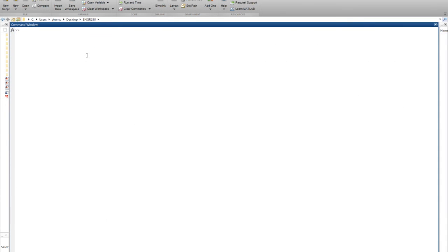Okay, the key for working with complex numbers in Matlab is that 1J is what Matlab calls the imaginary unit. Right? So every time we write down J, we're going to actually write down 1J. So I'm just going to enter the matrix that we had. I'm going to call that matrix A equals. Right? And it's a 2 by 3 matrix.